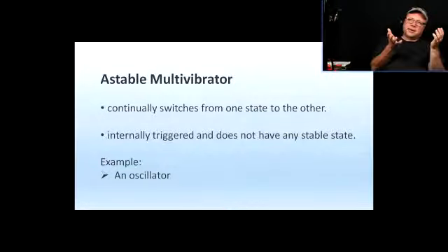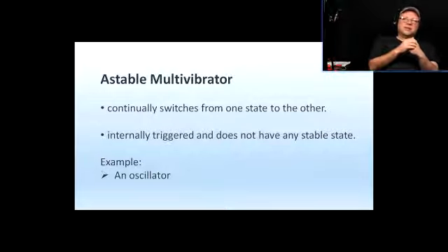And you're going to choose different parts or components to wire into that chip or integrated circuit or IC to make it go either faster or slower. So you're going to increase or decrease the frequency. And you can also add different components and different values of the components in order to control the duty cycle of it as well. You can make it generate pulses as well.